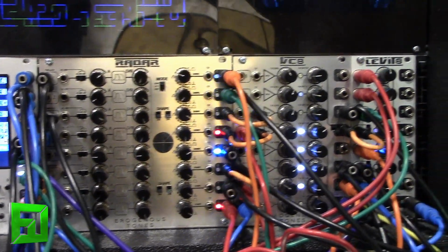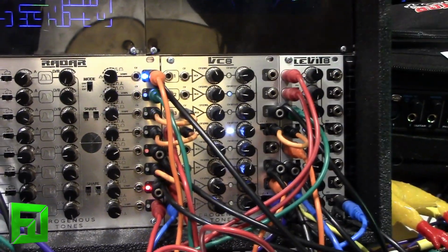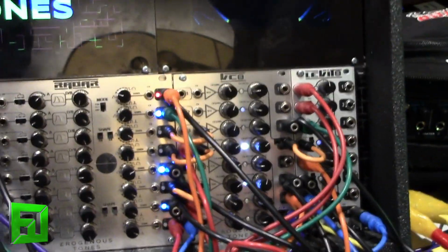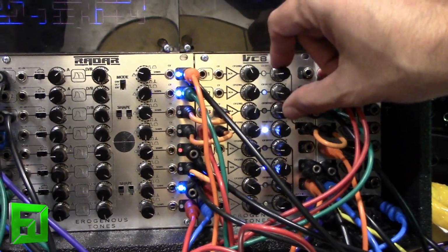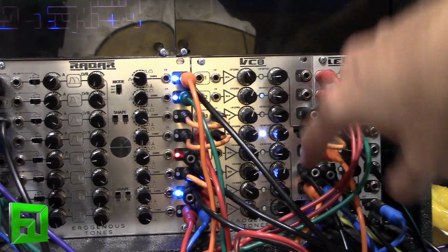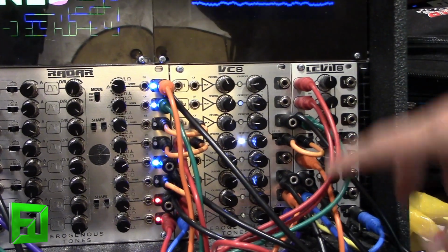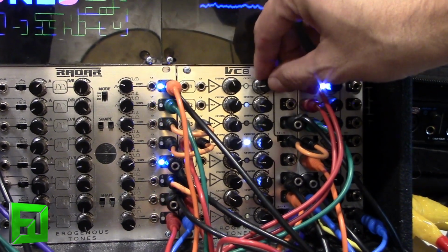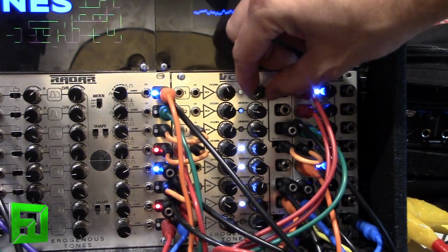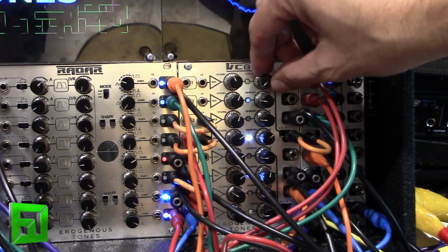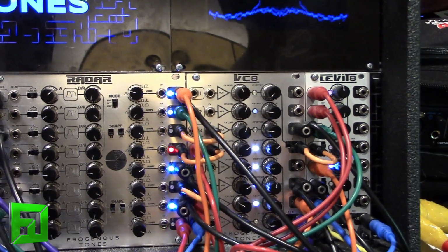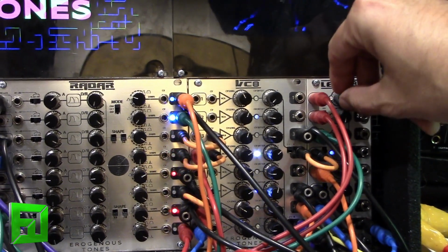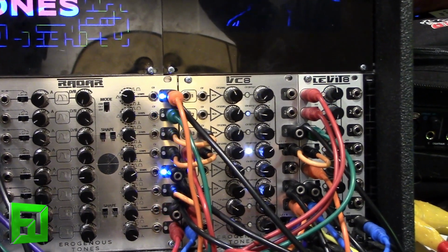And what is the VC8? So VC8 is 8 VCAs. Awesome. You can never have enough VCAs. I know, right? The same thing with the envelopes. You can feed 3 of them into the 4th one with this switch, so it's kind of like a subgroup type of thing. And instead of just doing a bias control, which I've seen a lot of, I did an offset control, so I could go negative. That way, when you put a negative on it, it shifts when the VCA is going to kick in later on. And if I need to make up some gain, I just use Levitate down here on the end. That's awesome. To pull it up.